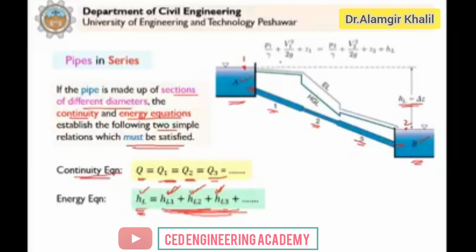When you apply the energy equation, the Bernoulli equation including the head losses, we have P1 by gamma plus V1 square by 2g plus Z1 at point 1, and this will be equal to P2 by gamma plus V2 square by 2g plus Z2 at point 2, plus HL. This HL is the head loss for the entire system. We now consider the entire system.